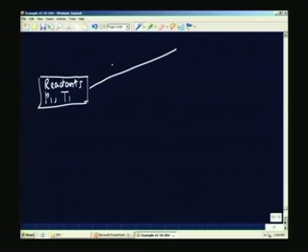In the bomb, we have, let me just show a box diagram. We have reactants. What are the reactants? The pellet of the fuel and the oxygen, which is at 20 bars or 25 bars. So, I will say P1 and T1. This is the condition. And this is the heat released in the calorimeter.